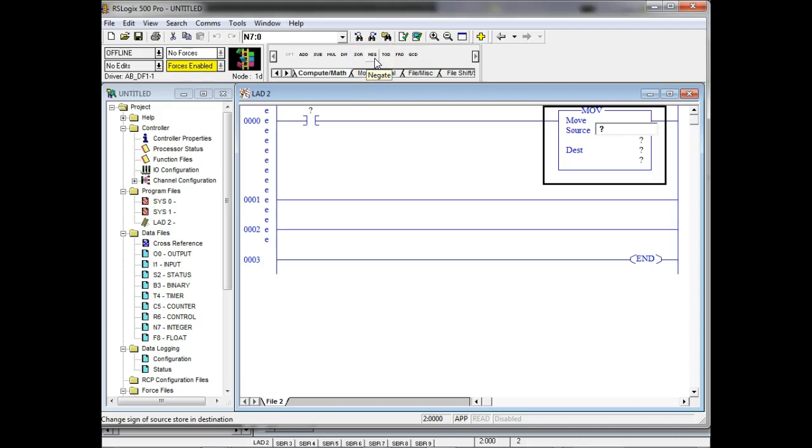If you have a positive number and you want negative, you can use the negate instruction. If you have a negative number and you want to make it positive, you can use this instruction. This instruction right here we'll use later on, TOD. What this does is it takes BCD information and converts it over to binary. Because all the numbers you're doing addition with are binary numbers, right? Even though your application is displaying them in decimal, thank goodness, the actual math is in binary.